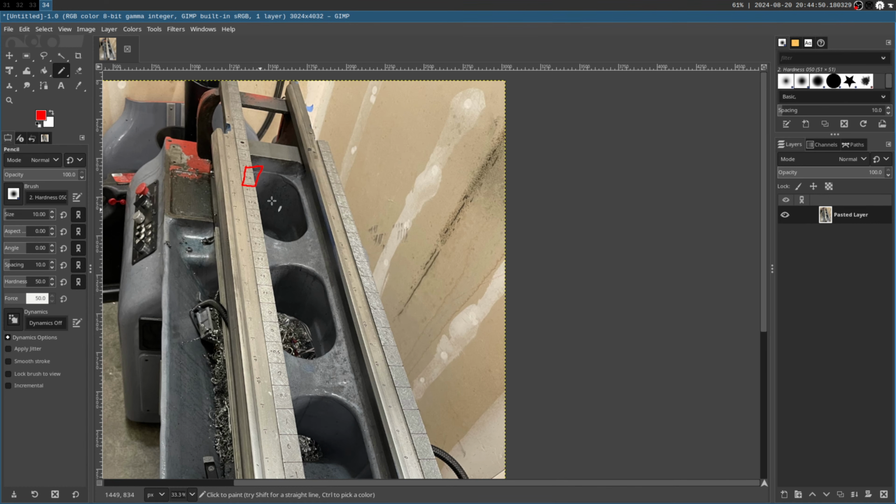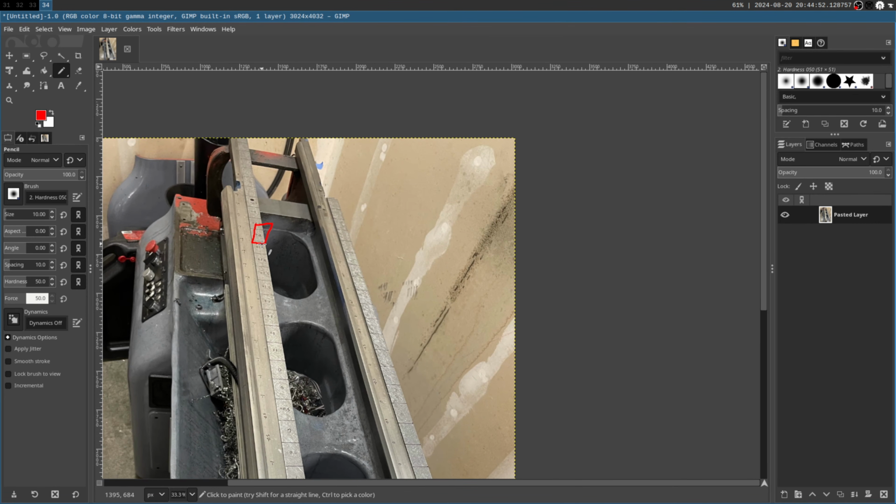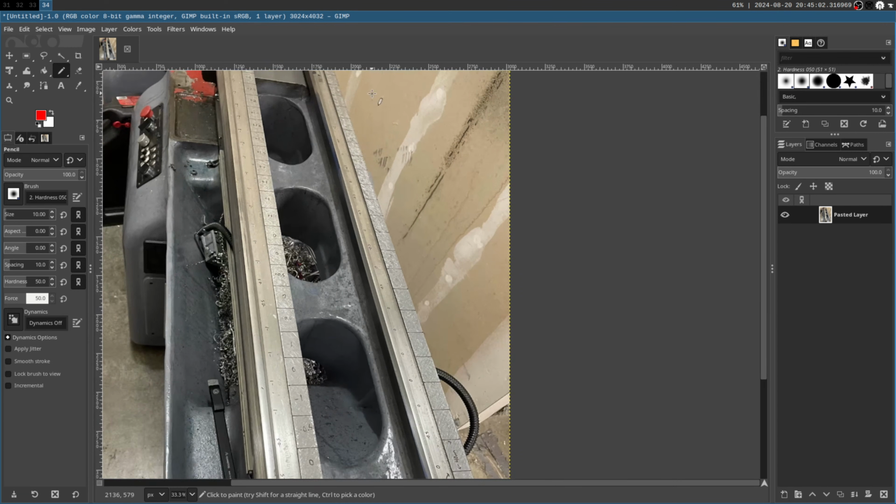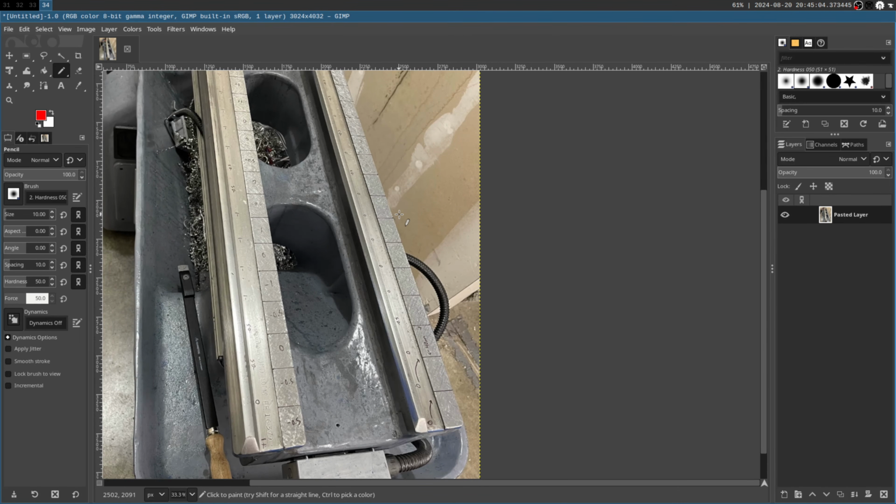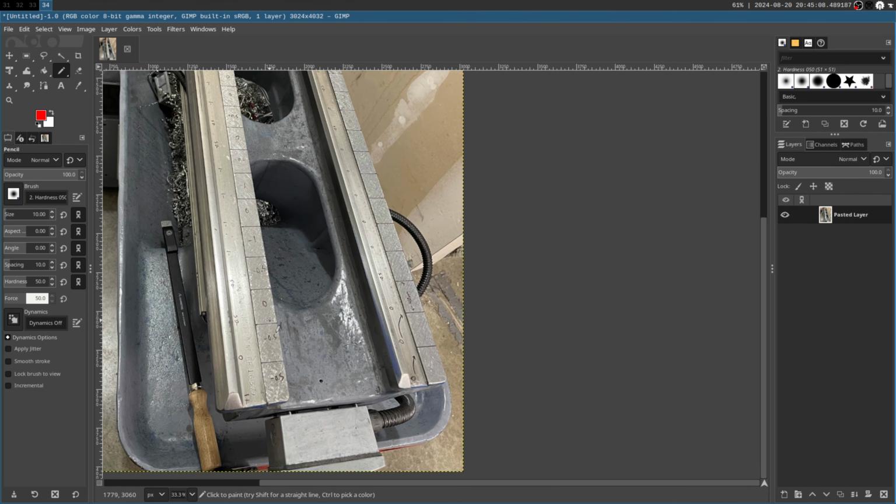Because the narrow cross-section of that straight edge has really not much information. It's so easy to tip that straight edge, so it's kind of the wrong way, and you get a bad reading, once again, right? So that leads to what I have actually been doing for the lathe, and that has been measuring level. So the only measurements that I have is the level of 2 points.